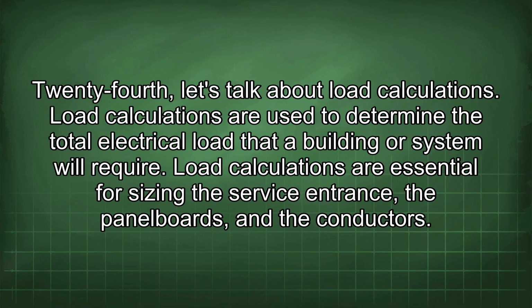24th, let's talk about load calculations. Load calculations are used to determine the total electrical load that a building or system will require. Load calculations are essential for sizing the service entrance, the panel boards, and the conductors.